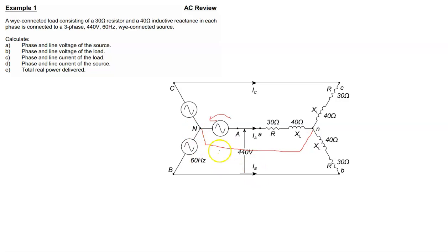One thing about connecting a neutral is that in some three-phase circuits, especially these Y-Y connected ones, we could take out a single phase and analyze that, and sometimes that becomes easier. If we took a single phase out of that, we've got V phase here, which we haven't calculated yet, but we will in a minute.